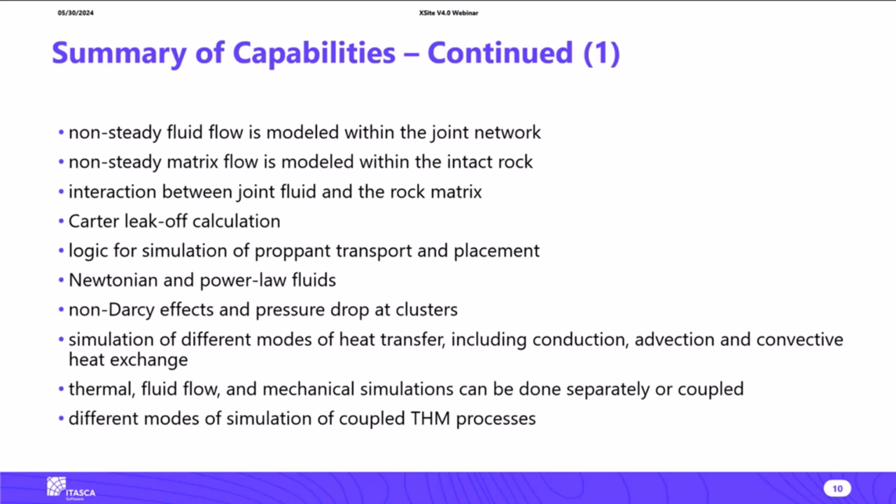So in reservoir scale models, of course, the detail of perforations cannot be explicitly represented, but we can still represent the perforation pressure drop in the model using formulas, which are a function of injection rate and the geometry of the perforations.